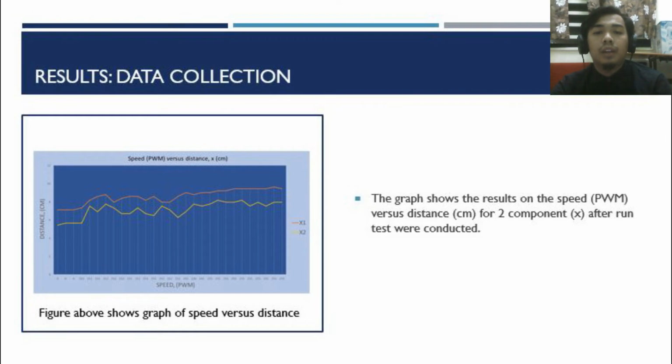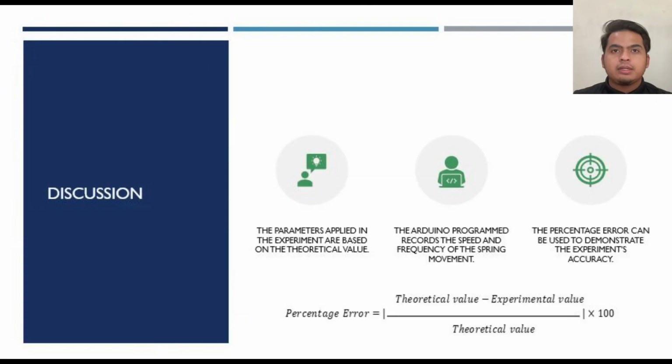This is due to the fact that car 1 distance x1 is connected to the crankshaft or spring holder, while car 2 distance x2 is connected to car 1 by a spring connection. In addition, the angular velocity is kept as a manipulated variable, but the angle of the crank is kept as a constant variable with a 45-degree rotation.